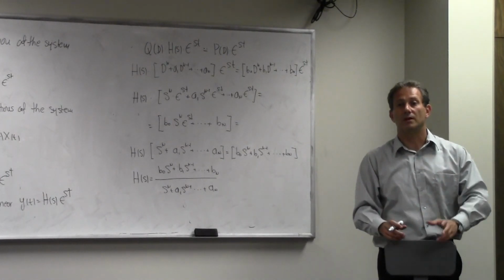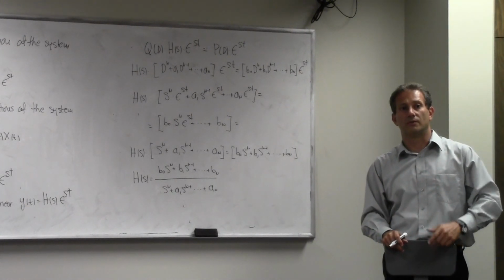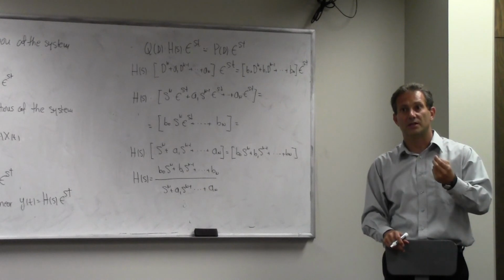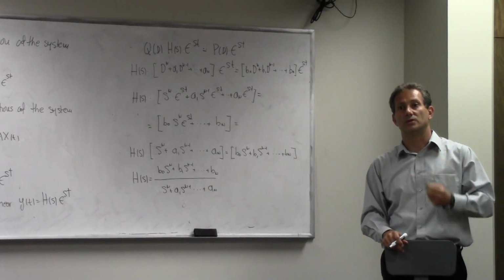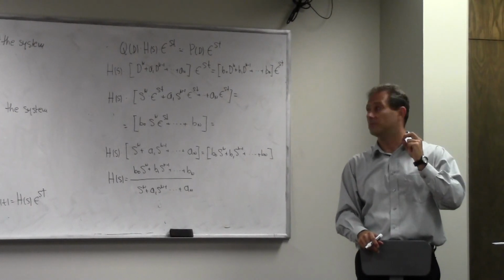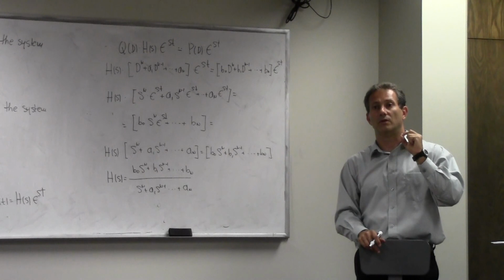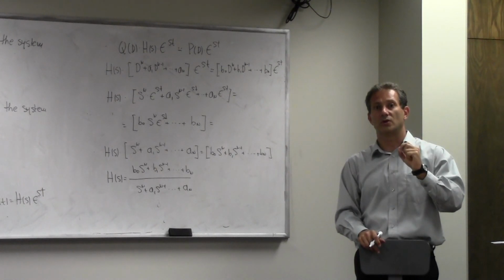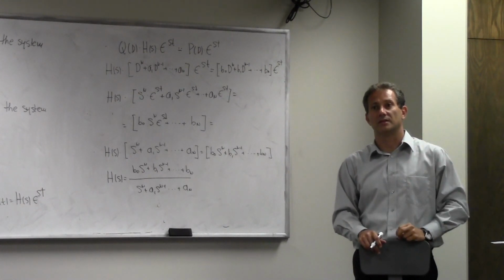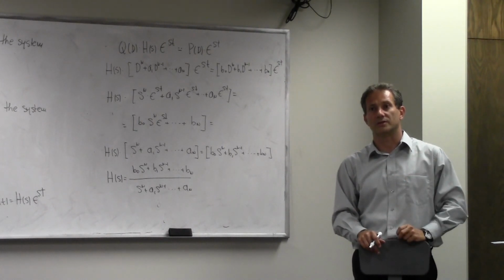Any signal, we learned that. We learned through Fourier analysis that you can take any signal and decompose it into sinusoids. And why do we do that? Precisely because of this. Obtaining the output of a linear system to a sinusoid is a trivial task. There are no calculations involved once you know the transfer function.